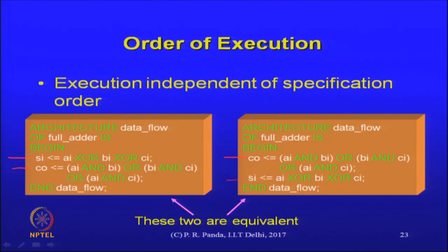Okay. This is as opposed to a sequential programming language, in which if you have one statement and you have another statement, particularly if there is a dependency between those two statements, then the order is important. If you interchange the order, you may get a different result. But here, if you interchange the order of specification, then you will not get a different result. How do you establish that, we will get to, but this is the rule of the language. A simulator that simulates your design has to obey that rule. And of course, we as designers need to know that rule also.